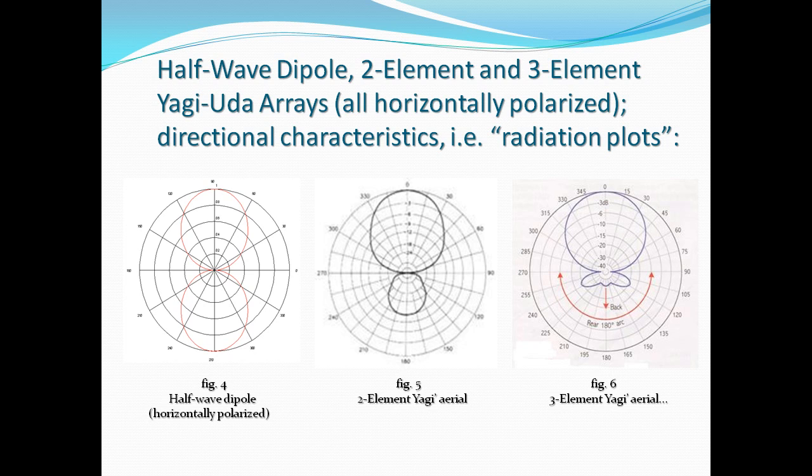the narrower main lobe, or it should look narrow, but there's a difference in scaling between these three polar diagrams. Consequently, figure 6, which shows the polar plot of a 3-element Yagi for another VHF allocation, should actually show the main lobe being narrower than the one in figure 5 and figure 4, but it doesn't because the scaling is different on the polar diagram graticule in question. It does, however, show the considerably decreased rear and back lobes of the 3-element Yagi aerial plotted.